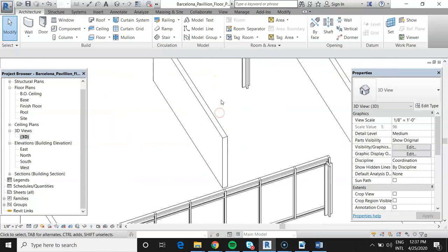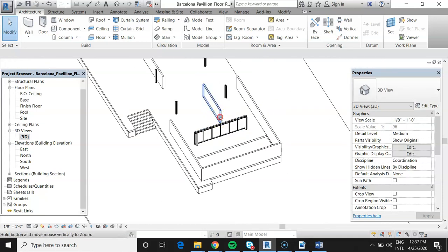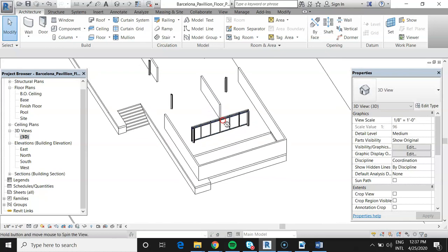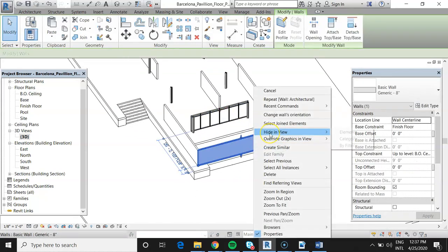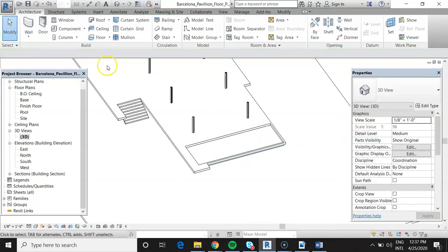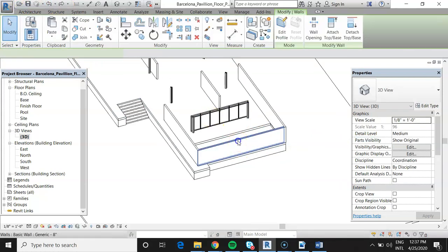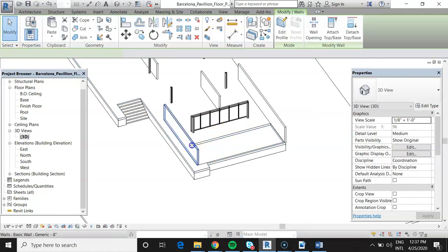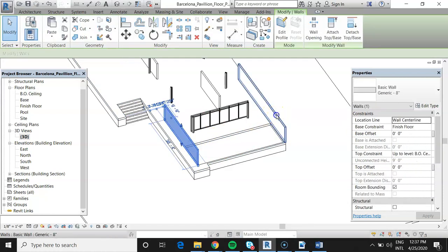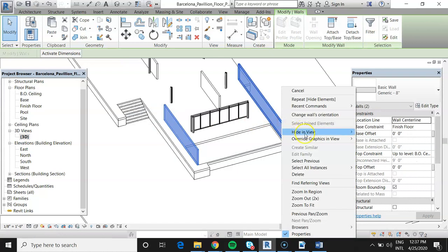Right, looks a little goofy. Needs some work. Let me hide these guys as well. We'll just hide the whole category. Oops, wrong, can't do that. Back up one. I can't hide the whole category, I'll hide the element. So hold the control button, select both, hide the elements.